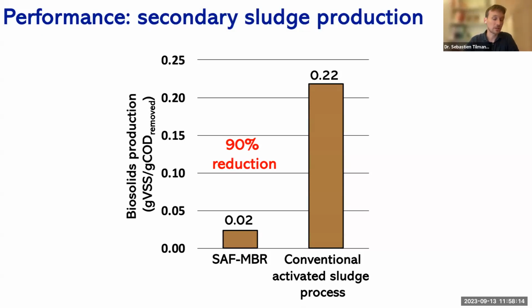So if you think about that, and then you take the primary solids, which we're still sending to anaerobic digestion, overall, you're reducing your total biosolids production by 30 to 50%. So that's a huge reduction in the number of trucks. You can think about it as taking 1 out of every 3 or 1 out of every 2 biosolid trucks off of the road and not sending them long distances to dispose of this material.